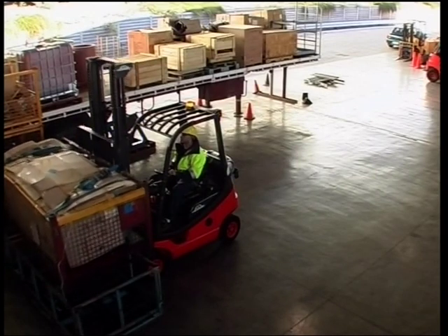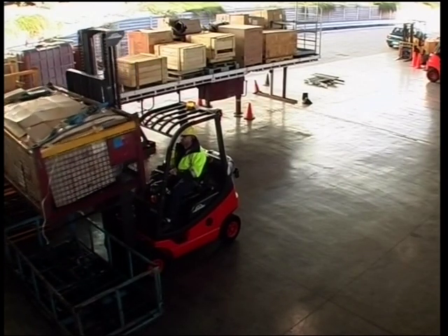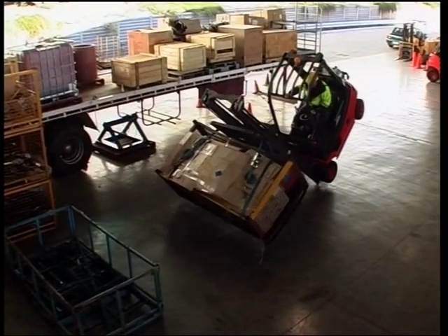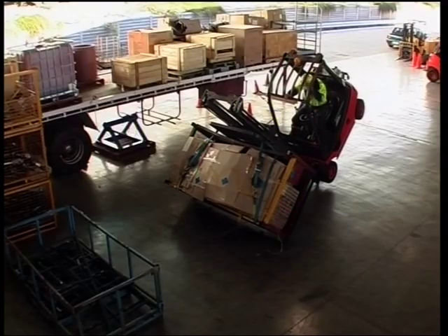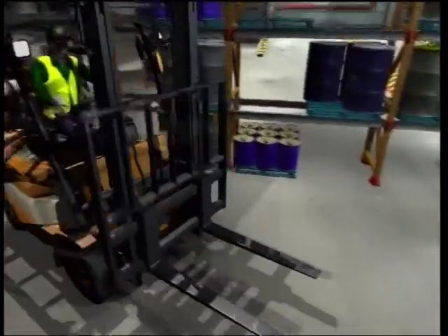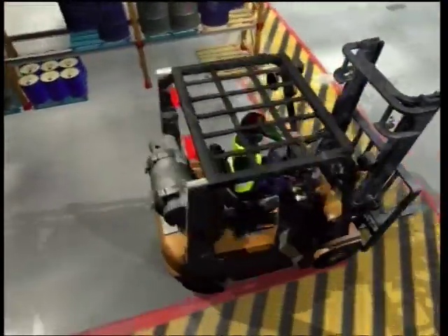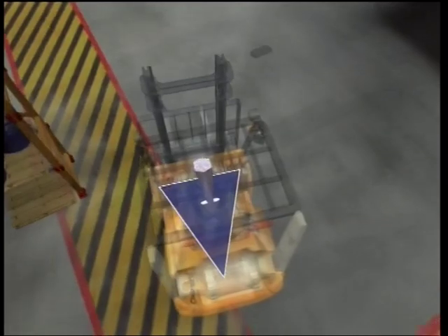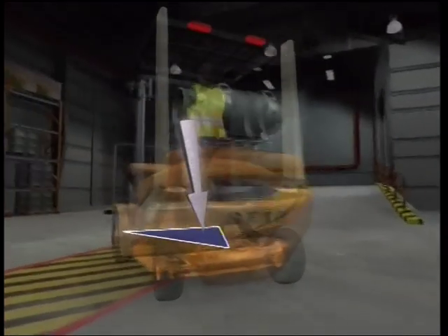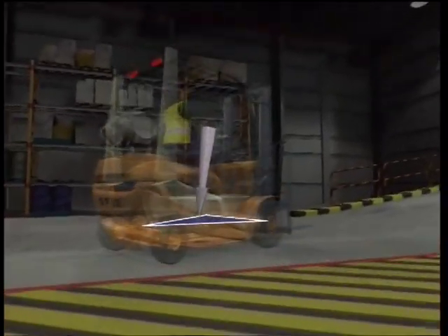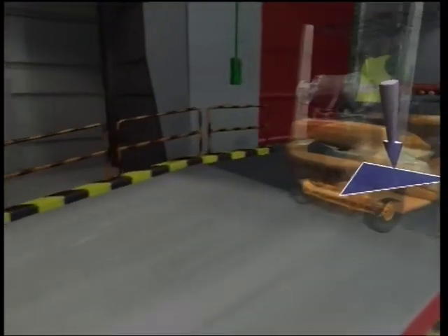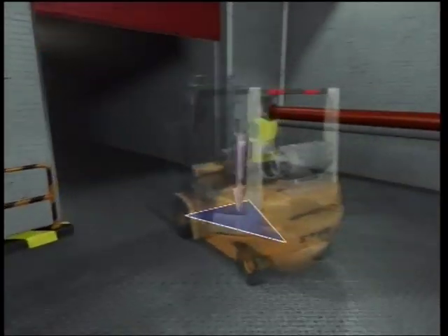A forklift may appear stable when it's static. However, dynamic forces that result when the vehicle and load are put into motion can be potentially fatal. To understand some of the dynamic effects when a forklift is moving, it may help if you think of a heavy steel arrow hanging freely from the center of gravity. This arrow will always point to where the center of gravity is acting when the forklift is turning, braking, or moving on an incline, and represents the apparent shift of the center of gravity.